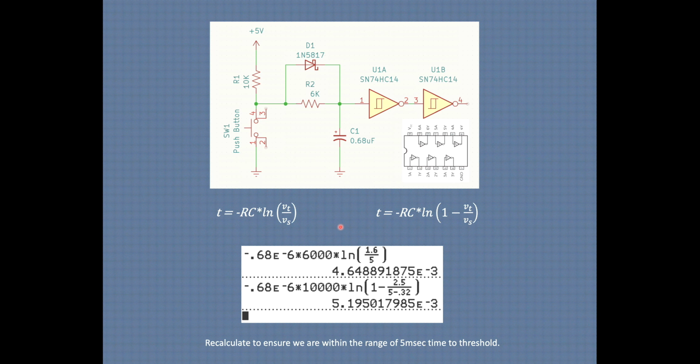So here we have the circuit. Now we're back to that circuit again. We've got our 5 on the charge and discharge. Discharge, charge. This one's a little less than the 5, but it's close enough. So you can go back through the prior slides. It takes a little while to get a hang of what we're actually doing, but the objective here is to get that timing so it's beyond the switch bounce.